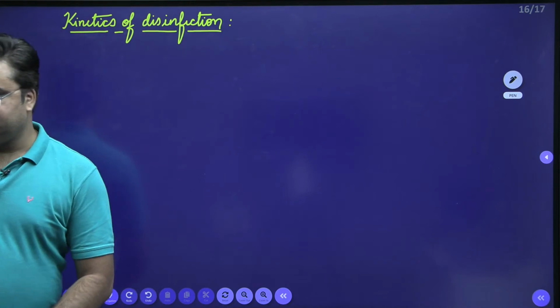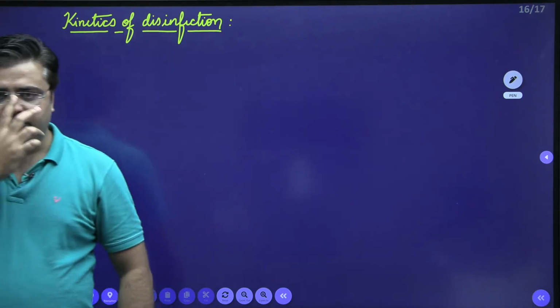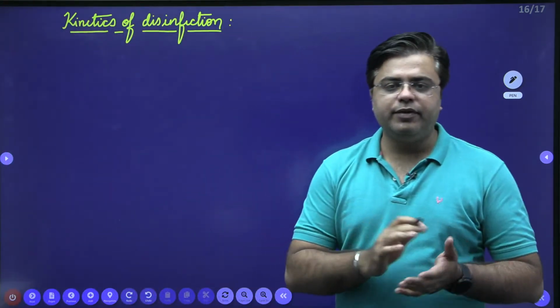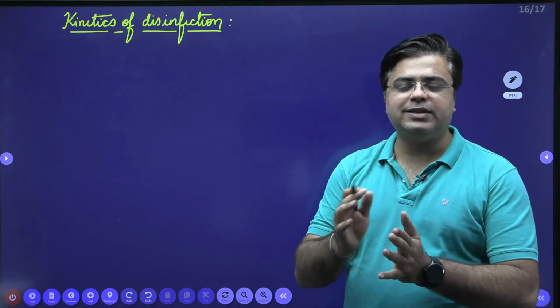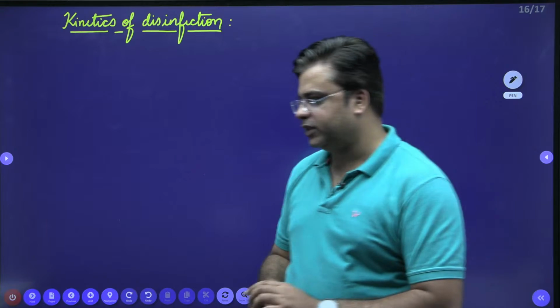How the disinfection is carried out, all those things we are going to discuss now. Here we will discuss how the microorganisms are getting killed when we are adding chlorine as a disinfectant.